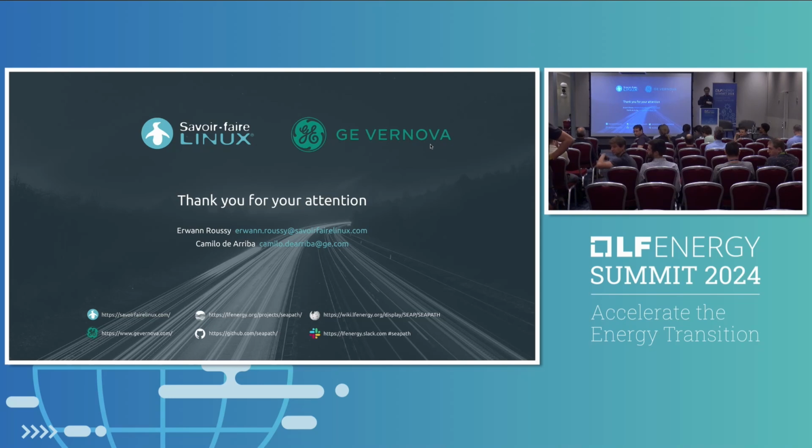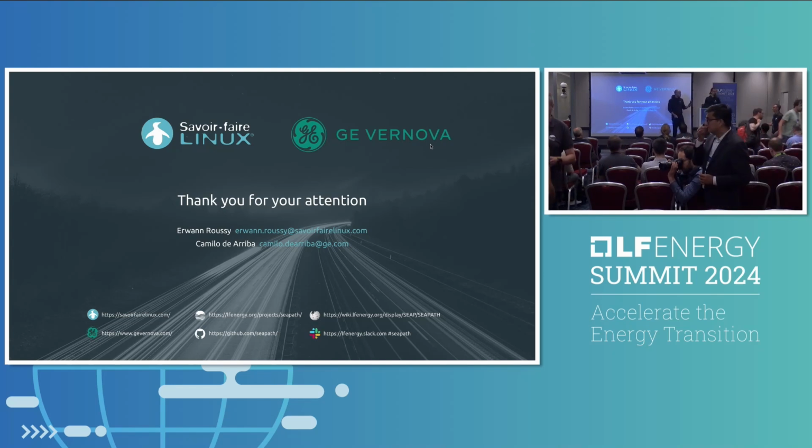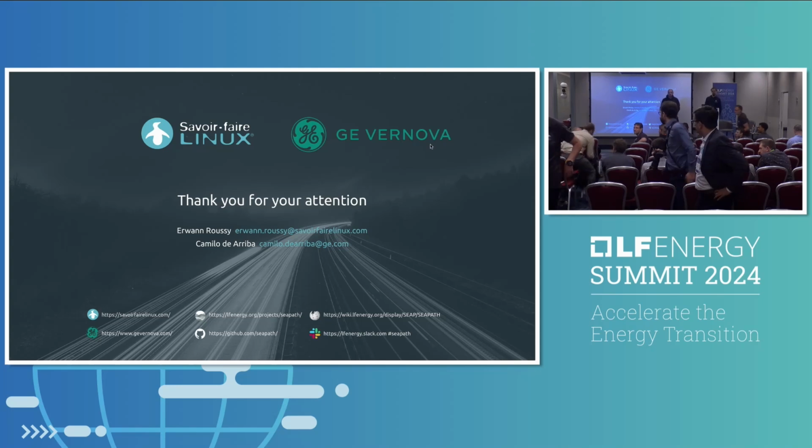Sorry, the time interface is normally provided by the manufacturers today between two protection devices if you make line differential protection. Do you think you can use a normal TCP/IP connection? Normally the line differential protection is a proprietary interface right now. Yes, line differential is because you have two ends, and I didn't think about that. We have to think about that. That's a very specific scenario. How do we manage that line differential protection?